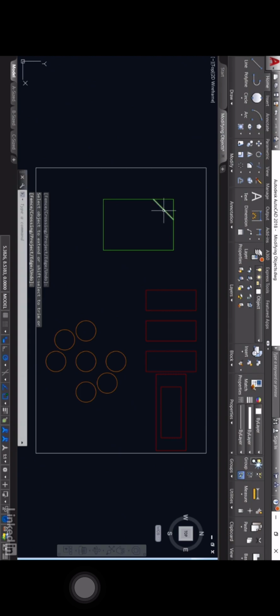This line can now be erased. I can just hit the delete key, and I've now got a nice simple rectangle that I've managed to get by trimming and extending. Now again, that's a really simple example of trimming and extending. And again, it might not be the same as the exam question you get in your certified professional exam. Again, I'm just getting you into the processes and the workflows of AutoCAD so that you can revise, review, and prepare for your exam.